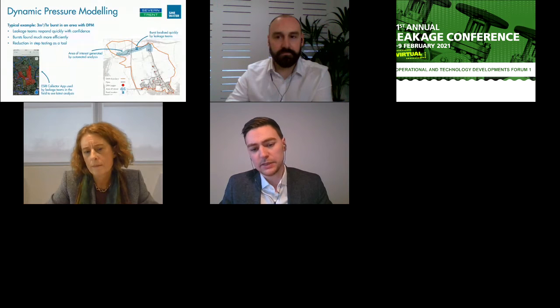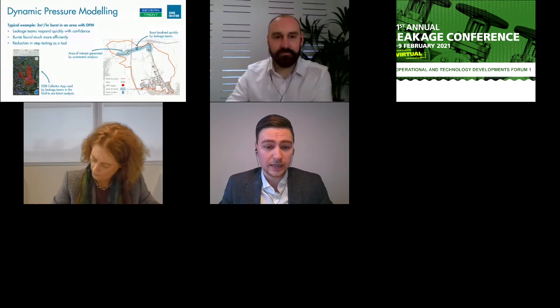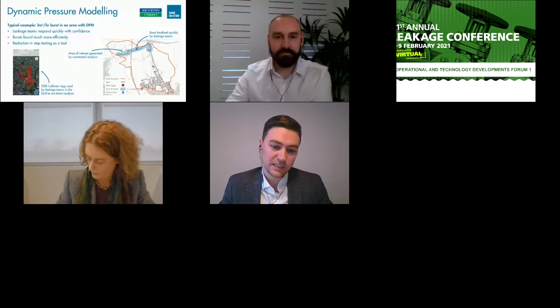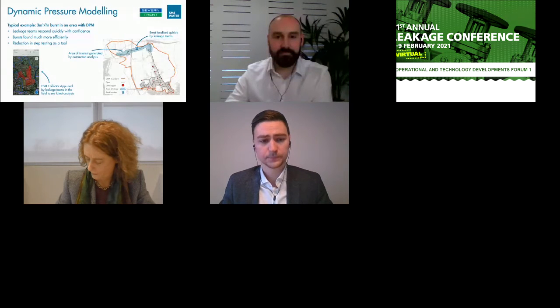It also has the added benefit, we believe, of reducing the need for step testing, because these are non-intrusive assets that give us smaller zones. So in terms of narrowing down the leakage we're looking for, we're not having to spend days, night hours, and also the disruption to the network that can be caused through step testing. So it's starting to limit that as a potential opportunity.